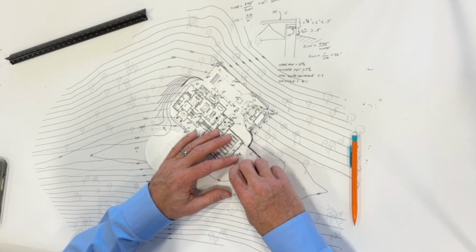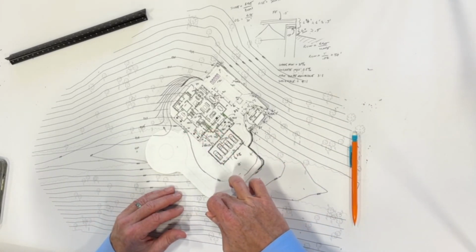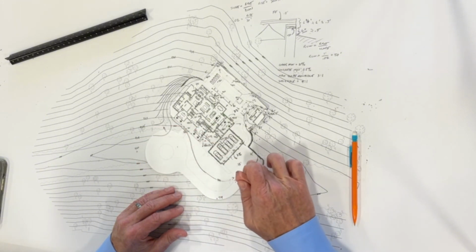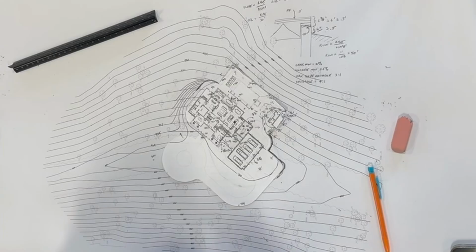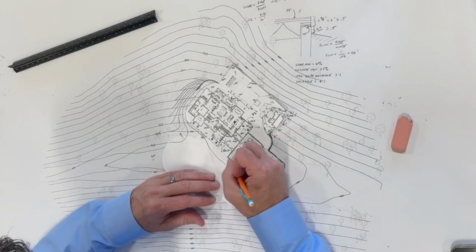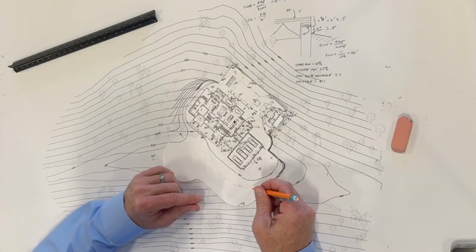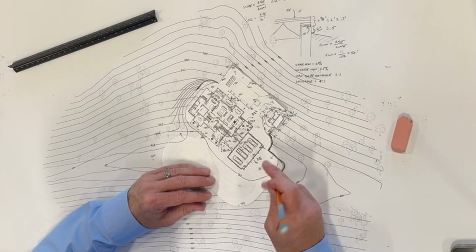And so if we do that, now what that means is the driveway is going to drop. You're going to be here, go downhill, and then back up, which might be all right, though, to save on retaining walls. I don't know, it's a big deal. All right, so now what we did is we pulled the 940 contour closer to the house instead of being out here. So now we're going to try to ramp this down to avoid a big retaining wall there. So we're going to have a flat driveway.